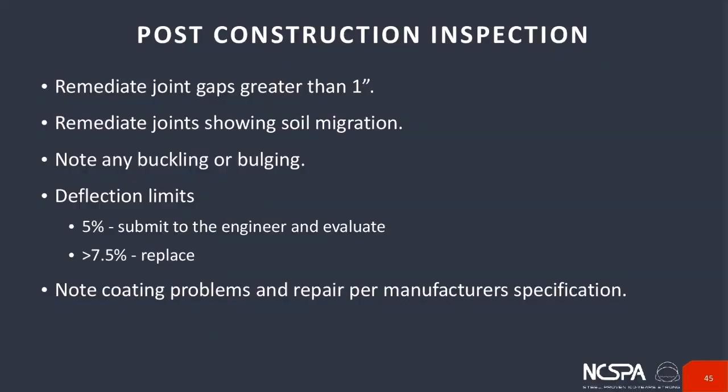So during post installation, a couple of things that you actually want to look for. You want to look at your gaps in your pipe, in your bands. Anything over 1 inch, you probably want to look at that and remediate it. You also want to look for soil infiltration and exfiltration. Like we mentioned earlier, if you have that, that's going to cause trouble down the road, because you're going to get loss of compaction in the soil that surrounds the pipe. So if you do find that in a band or a joint, you want to remediate that.